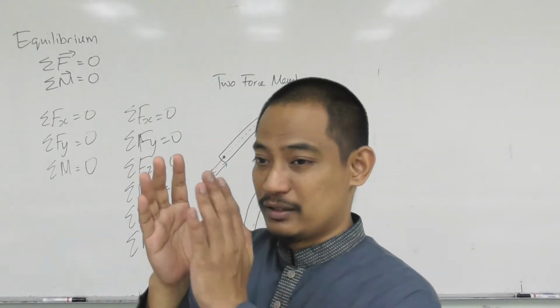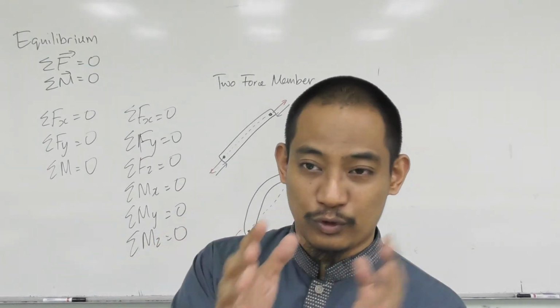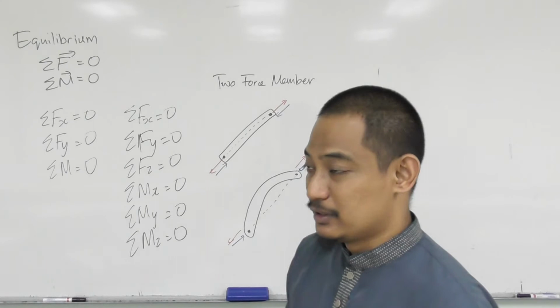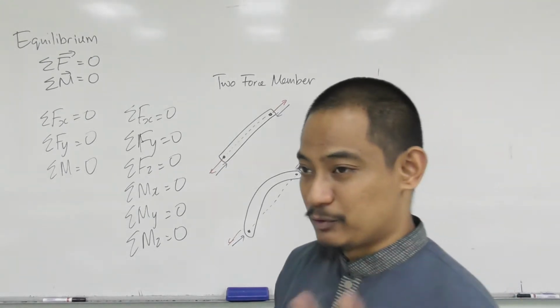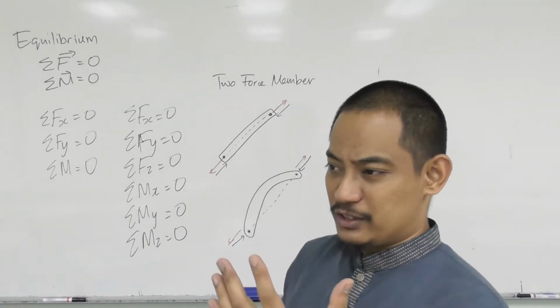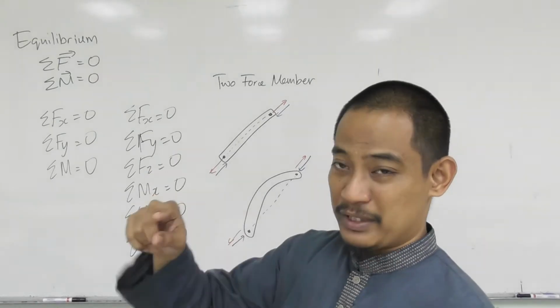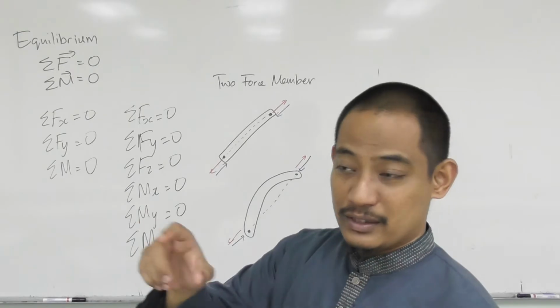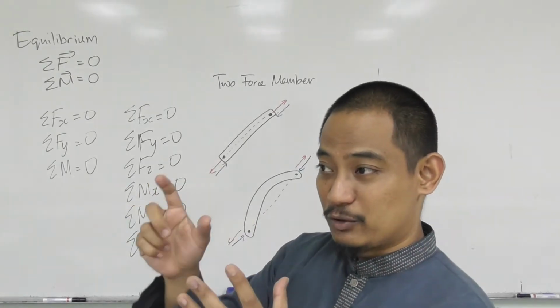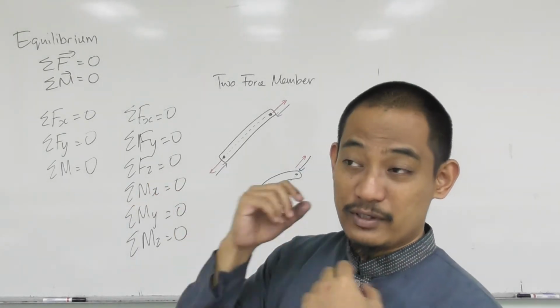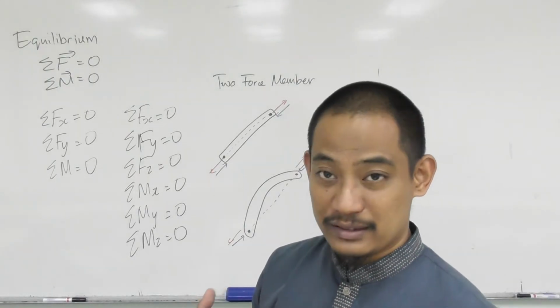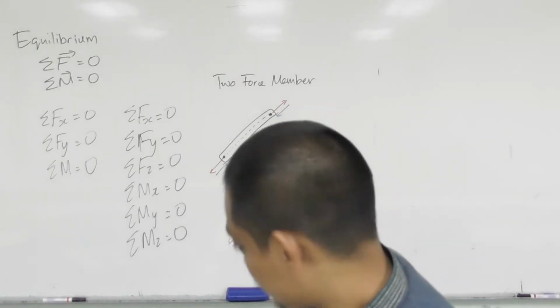So you can see that there's a possibility of 1, 2 or 3 unknowns. So in total, the number of unknowns will be different also. Sometimes the question asks, what if we change the support? Initially it's a pin, where you have 2 unknowns, and then suddenly it becomes fixed, and you have 3 unknowns. Sometimes in total, the number of unknowns becomes more than the equations that you have. Hence, you can say that, okay, in this case, it is statically indeterminate. Right? So I'll just write it.